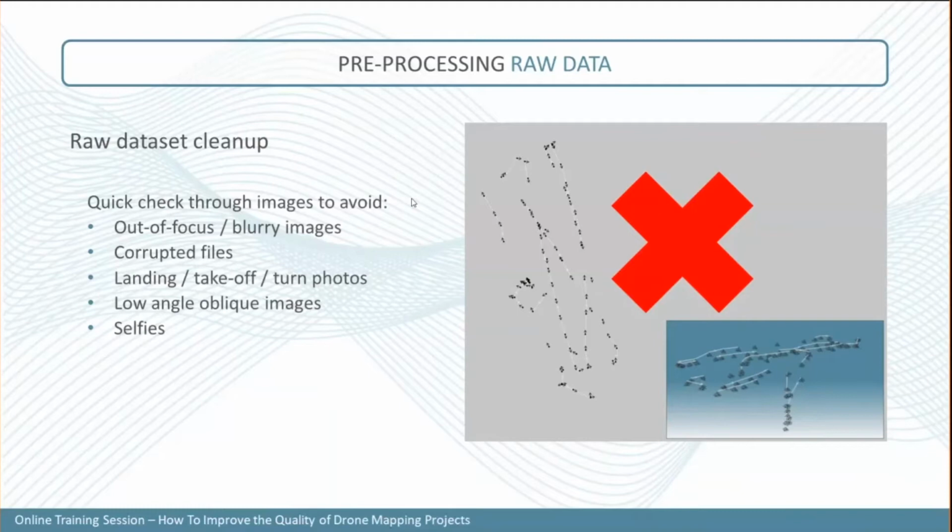But also when the drone is turning from the first flight line to the next one, it creates some images where you can see quite far from the areas of interest, where it's not the best condition to play with those images. So maybe remove the images where the drone is turning at the end of the flight line. You'll see sometimes that the yaw or the kappa of the drone will change a bit, and also the pitch and the roll, or the omega and the phi, might be a bit higher than the rest of those images. So you can remove those images.